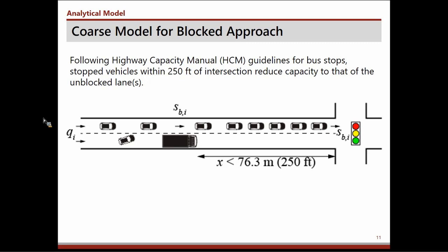And what that would look like in a situation like this on this street is that when that truck is making a delivery or that bus is making a stop, the vehicles can queue up only in one lane. And when the light turns green, they can only discharge at whatever capacity, the flow rate, saturation rate, was able to get past the truck. And this gives a coarse approximation. It certainly would reduce the capacity of the roadway compared to what it would have been otherwise.